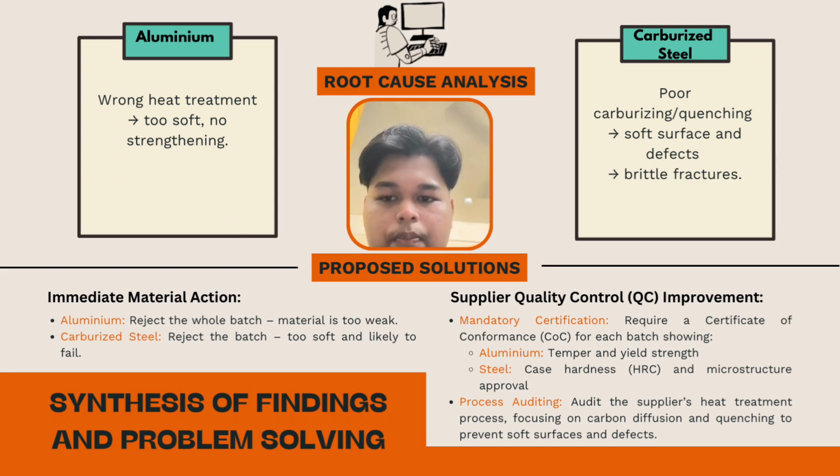And lastly, for proper solutions, we recommend two key actions, which are mandatory certification for each batch, ensuring quality control through certificates of conformance, and process auditing, focusing on refining the supplier's heat treatment process to prevent defects.